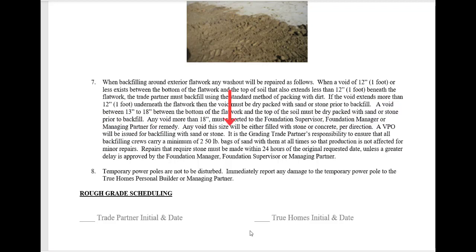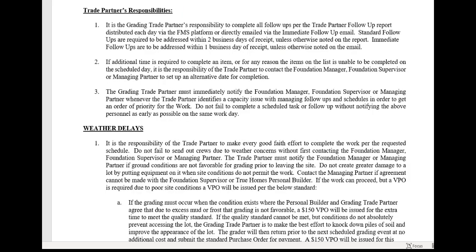It is the grading trade partner's responsibility to ensure that all backfilling crews carry a minimum of two 50-pound bags of sand with them at all times so that production is not affected for minor repairs. Repairs requiring stone must be made within 24 hours from the original request date, unless a greater delay is approved by the foundation manager, foundation supervisor, or managing partner. And then number 8, temporary power poles are not to be disturbed. Immediately report any damage to the temporary pole to True Homes personal builder or managing partner.